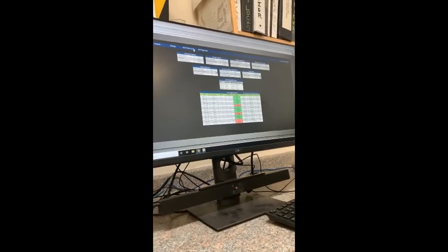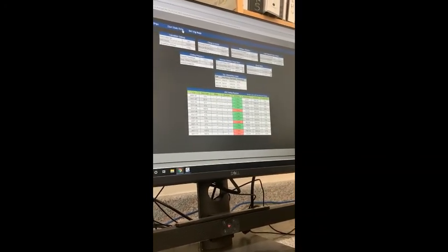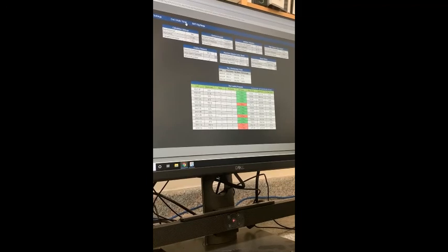Just like how the pumps work for the chilled water and hot water system, the air handlers will look at the VAV damper positions to increase or decrease duct static pressure. It'll also look at the load and increase or decrease the supply air temperature as well.